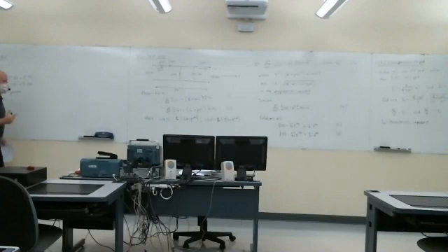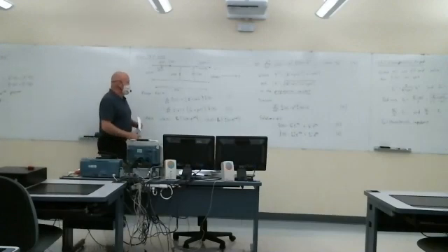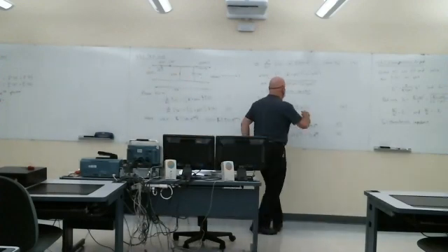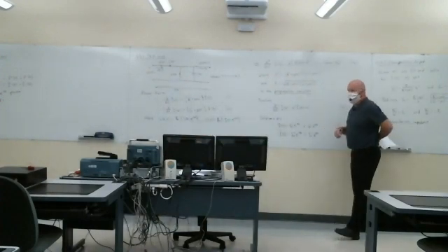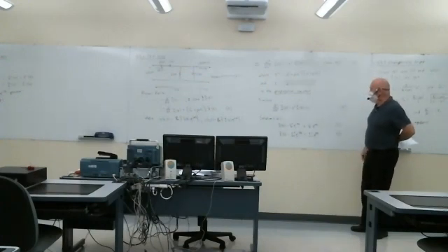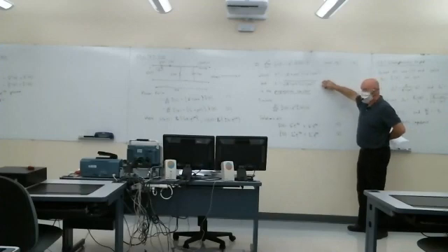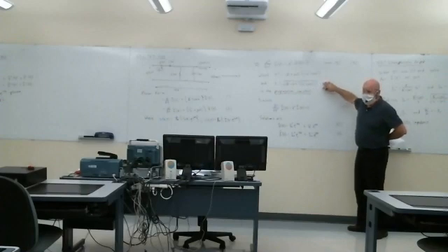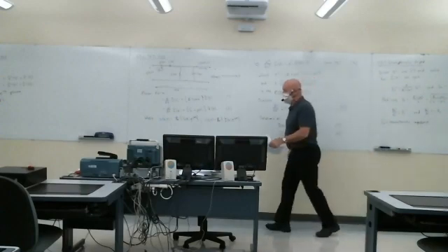And our propagation constant, which is the square root of (R' + jωL')(G' + jωC'), is in general certainly going to be complex. In the low loss case, we'll have (jω)², that would actually come out, and we would just have jω, and it would be entirely imaginary. But in general, it's complex.